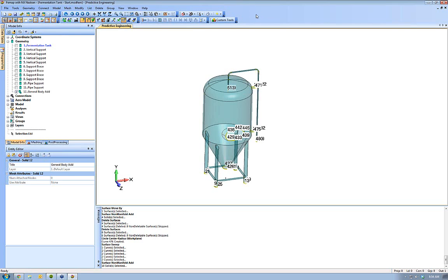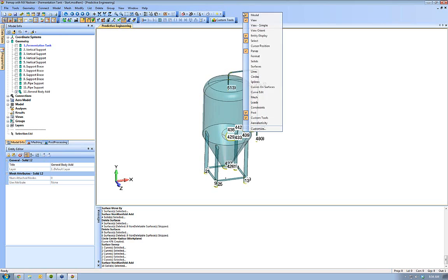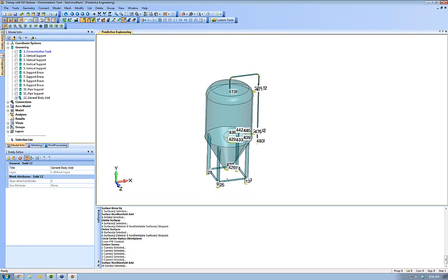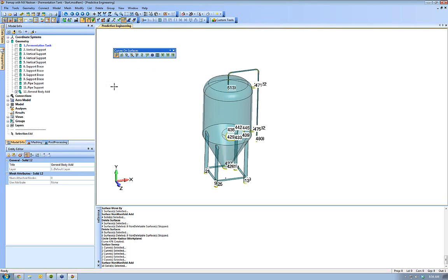I'm going to start with the curves on surfaces toolbar. If you right click up in the blank space up here, this is where you turn on and off all of your toolbars. And what we want is curves on surfaces. So I'm going to turn it on. I'll drag it out here so you guys can see. This is a lot of commands that are aimed at working with sheet solids. They never really split it up into multiple solids, but they do split your surfaces so you can help propagate higher quality mesh.